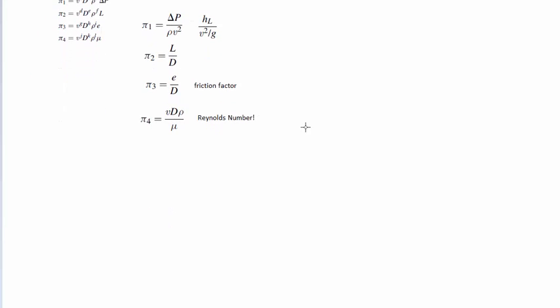If you remember your Buckingham Pi theorem, it says that you could write one pi group as a function of the other pi groups. That's exactly what they did, and that looks something like this. So here we're writing this first pi group as a function of the remaining pi groups, with this proportionality constant of phi 1.